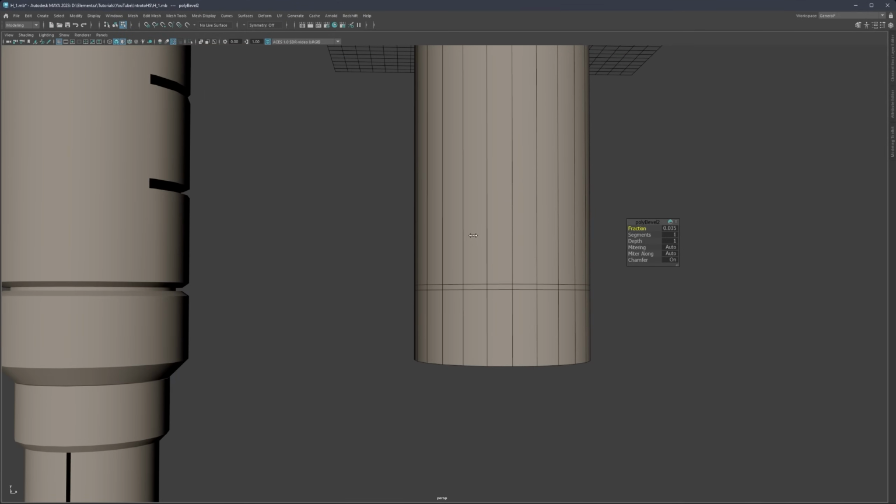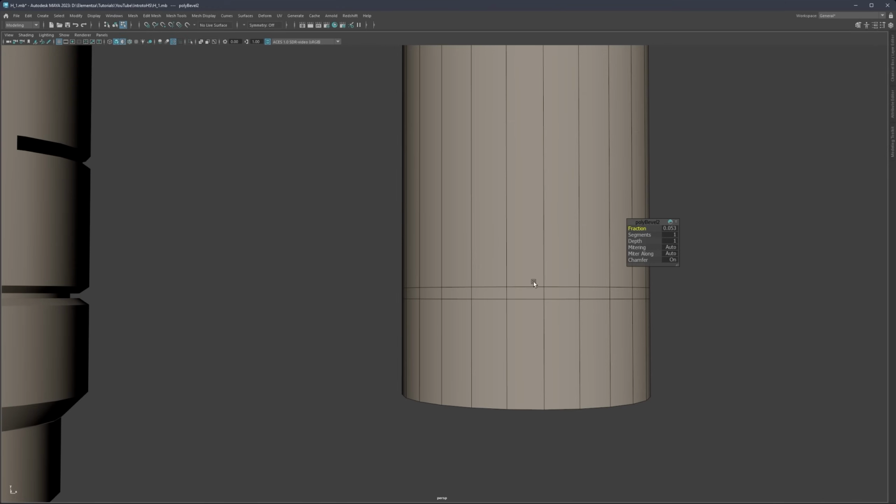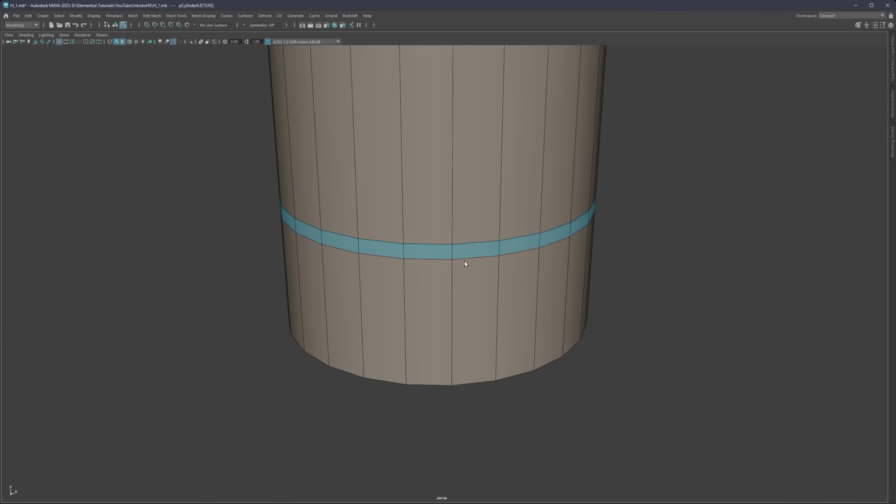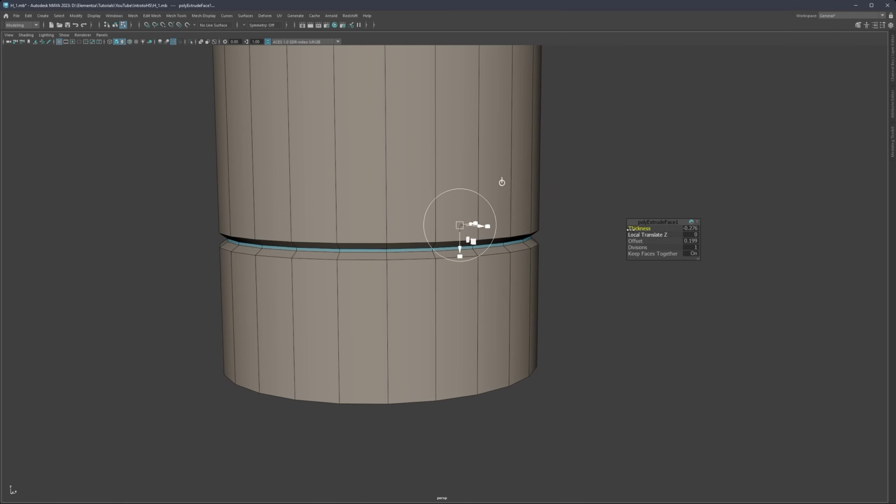Now let's do a bevel. Let's do a whole fraction. And let's say something like this. Hit Q to confirm. Let's go to face mode, click once and double click to create a loop while holding shift. And let's do now extrude faces. And slowly now I'm going to start using hotkeys. So for every one of these operations, I have a hotkey. And let's now push this on the inside like so and hit G one more time.